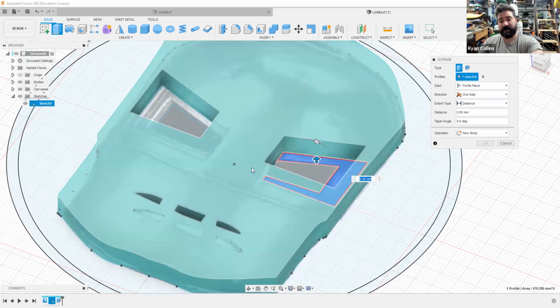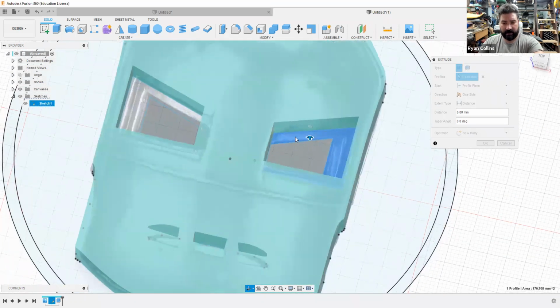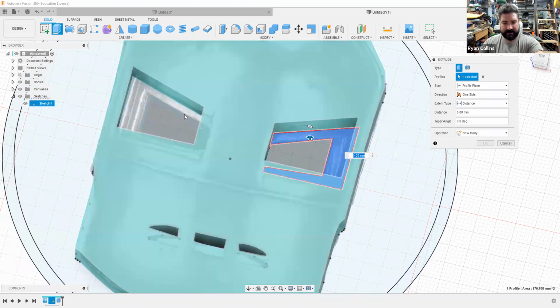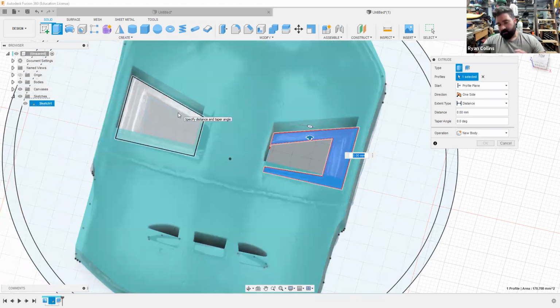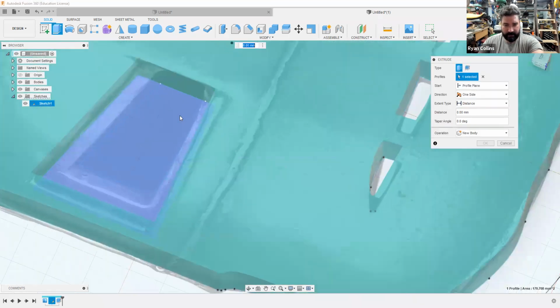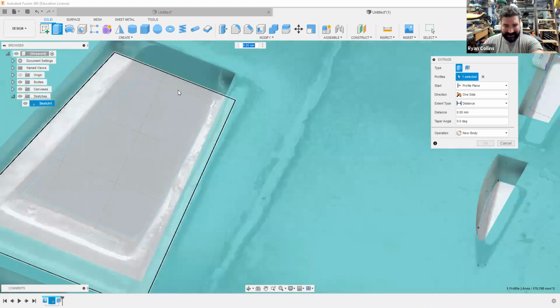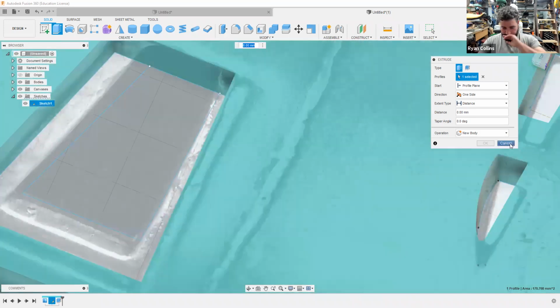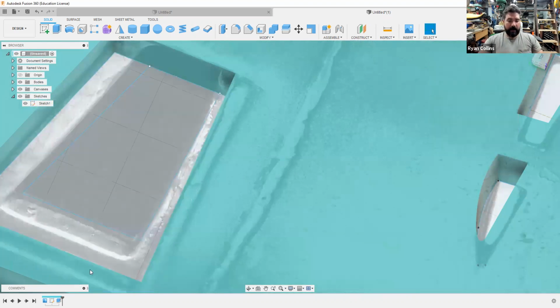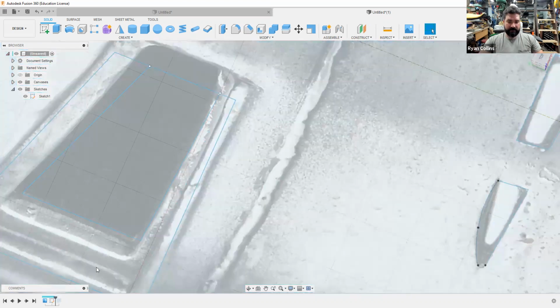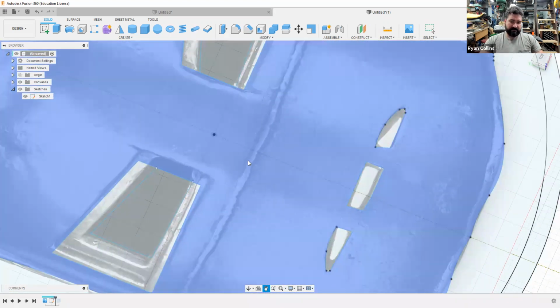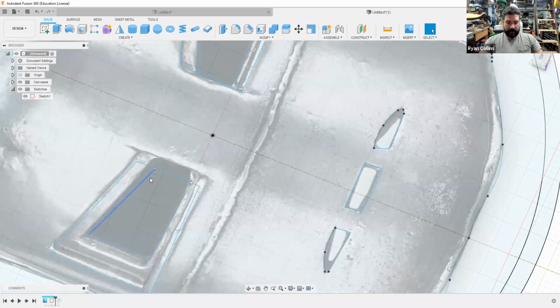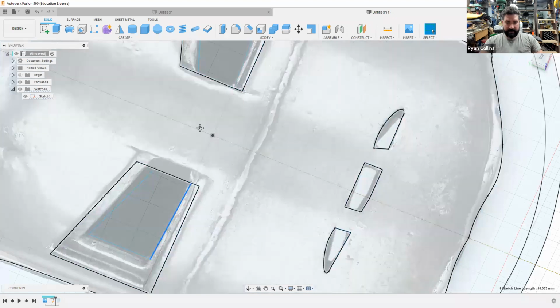All right, so this is something that happens. If you notice that, all right, I've made these symmetrical, why am I not able to select the same one on both sides? What might have happened when I did the mirror tool is that one of the lines, for whatever reason, did not get mirrored. So, pardon me, hit cancel. And I'm going to use the history slider to slide back before I did the extrusion. Not that you have to do that, it just sometimes helps to see what you're doing. And for whatever reason, it's not connected.